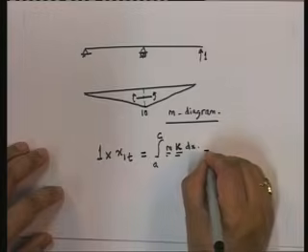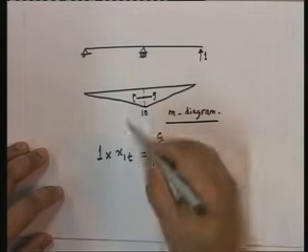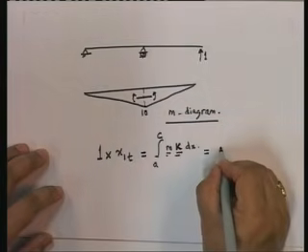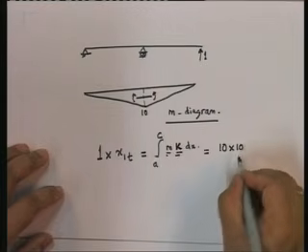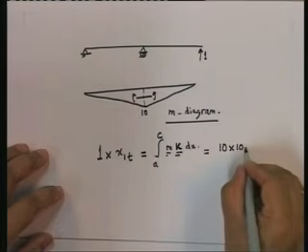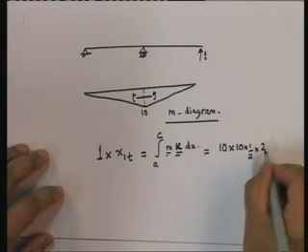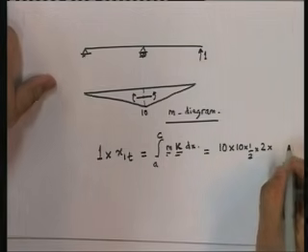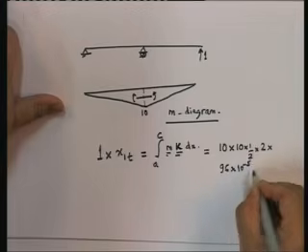And so if I put that, this is going to be equal to, what's the moment? Again, the integral is the area of the moment. If you look at this particular one, the area would be equal to 10 into 10 into half into 2 multiplied by kappa, which is this value, 96 into 10 to the power of minus 5.